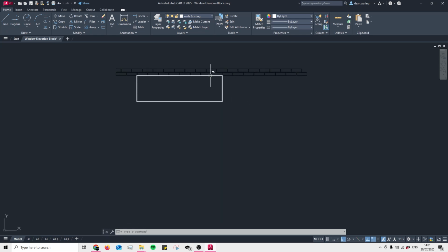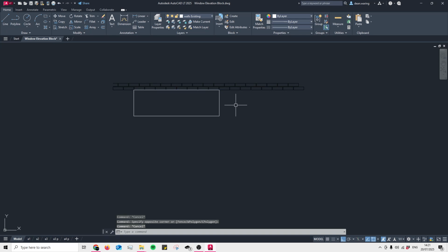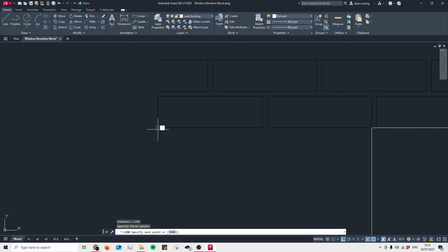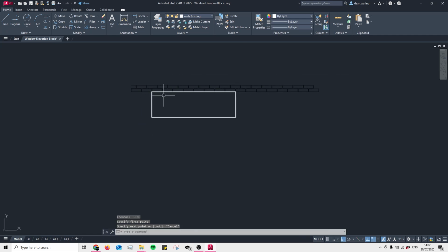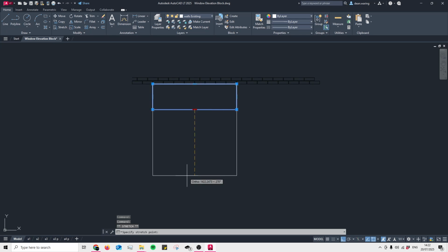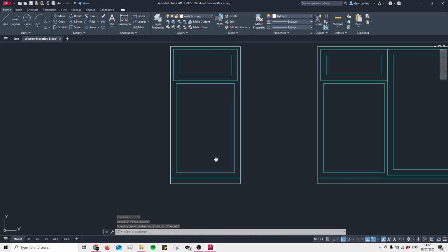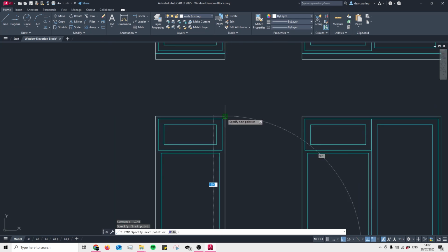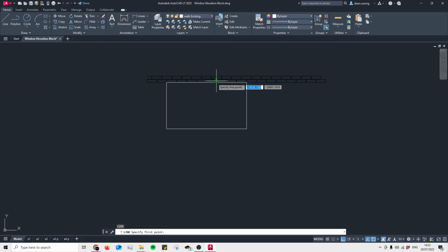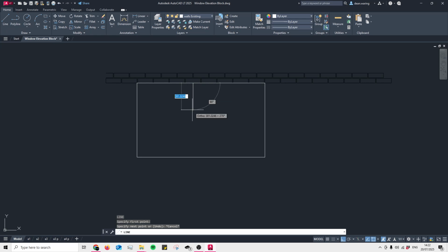Now we need to make sure that the height of it is also a brick dimension, and this would mean that it needs to be a multiple of 75. So as you can see, the bottom of this bottom brick to the bottom of the top brick is 75 millimeters, meaning this needs to be a multiple of 75, and I happen to know that 1050 is a typical size, so I will just use that. And as you'll be able to see on these templates down here, we have 1200 as a standard length as well. So 1050 and 1200. I'm going to change this to 1200.